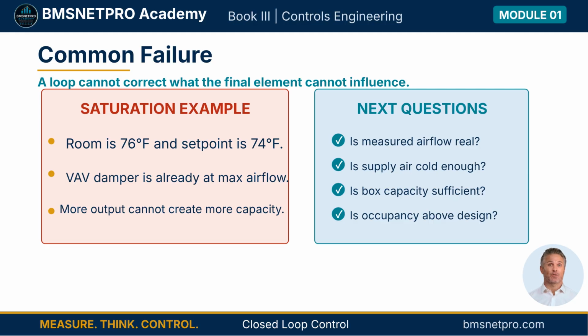Is the airflow measurement real? Is the supply air cold enough? Is the box actually at its physical maximum? Has occupancy or solar load exceeded design? A good controller identifies the demand. A good engineer investigates why capacity is insufficient.